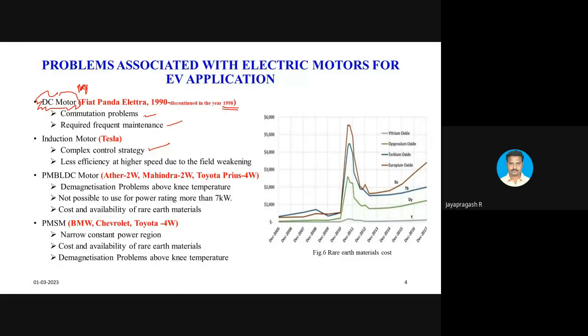As I said, even if you make a slight change, for example, if you are reducing the supply voltage by 2 or 3, or by 5, there is a drastic reduction in the torque also, right? Because the torque is directly proportional to the square of the supply voltage in the stable region. So there will be a reduction in the torque, but the shaft of the machine is always coupled with the load. Whenever you decrease the supply voltage, we may not decrease the load coupled with the shaft of the machine. It should not be practiced. So whatever may be the supply voltage variation, your machine should be in a position to supply a sufficient amount of torque to operate the load coupled with the shaft of the machine.